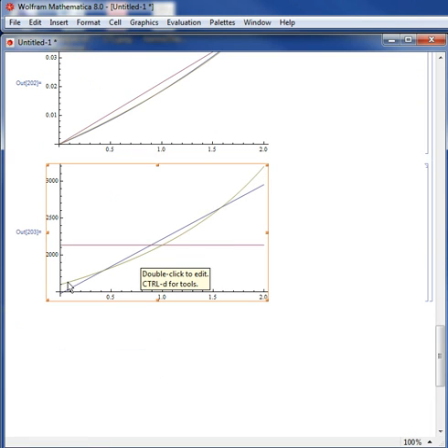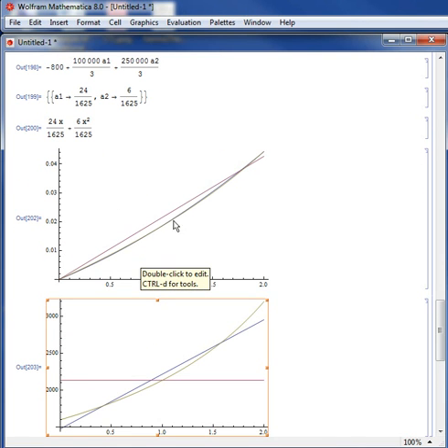this curved function. The first polynomial, when I use the displacement to be linear, the stress is constant because the stress is equal to E multiplied by the first derivative of the displacement. So I get a constant function, and then I get a linear function. So you can see the stress is really not close to the exact. The approximation for the stress is not very good. It's not as good as the displacement.